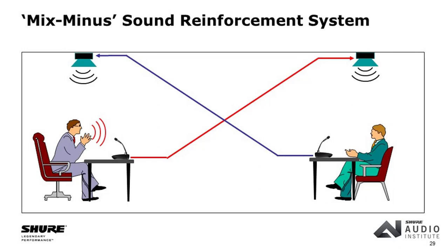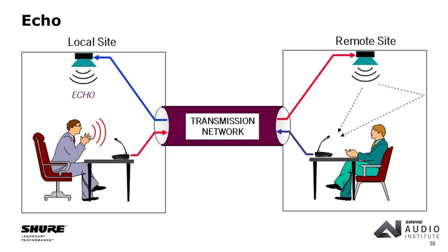And by doing this, now we've made that distance from the microphone to the loudspeaker much, much greater. And that, again, is going to allow us to get better gain before feedback. So you see this often applied in conference rooms.